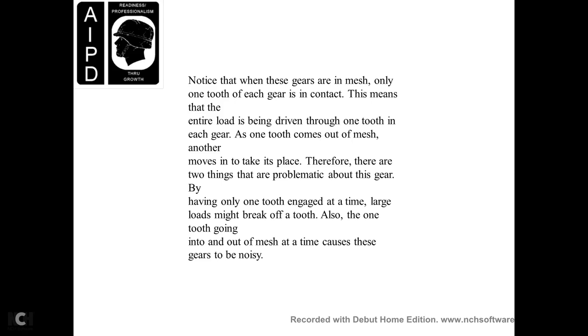Therefore, there are two things problematic about this gear. By having only one tooth engaged at a time, large loads might break off the tooth. Also, each tooth going into and out of the mesh causes the gears to be noisy.